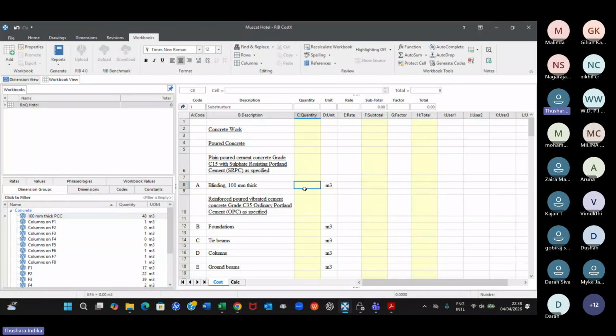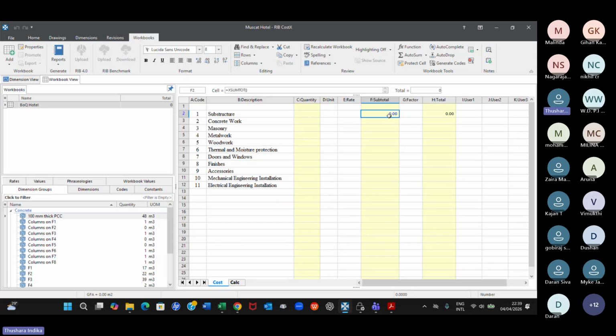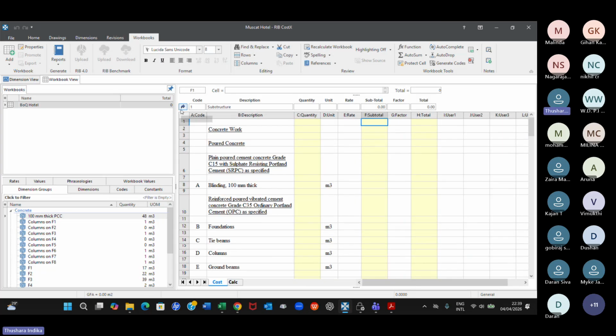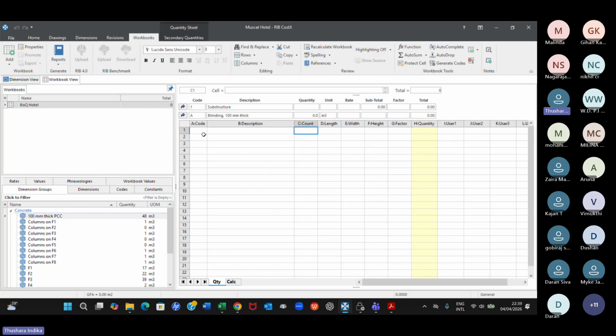So we don't do that. What we do is you double click on the quantity column this time. Earlier it was the subtotal column. Here also you have a subtotal, we don't go there. Here, summary level subtotal, level 1 for level 2 BOQ level, and there the quantity column is the cell where you need to insert the quantity. So we double click on that and then we go to another level called level 3. In my language, I used to call it the measurement level.